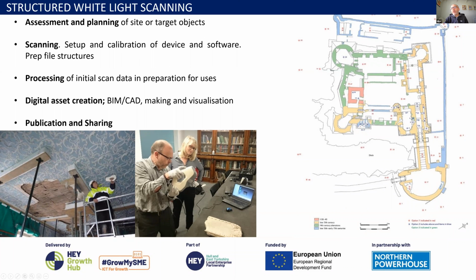We'll meet with the client, we'll take lots of the architectural drawings that they may or may not have. We'll agree with the client where we need to position the scanner, and also we'll need to make sure that we've got access around a structure. So if we're asked to scan something in spring when things are beginning to get overgrown, we might need vegetation cut back so that we can get all around access to the structure.